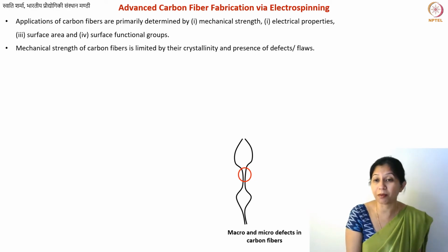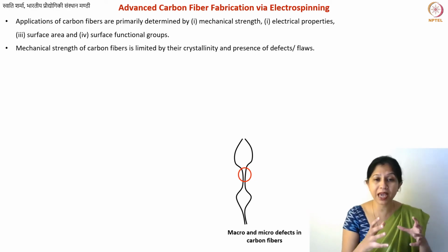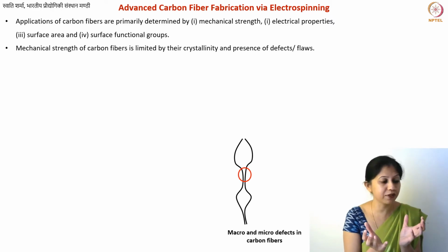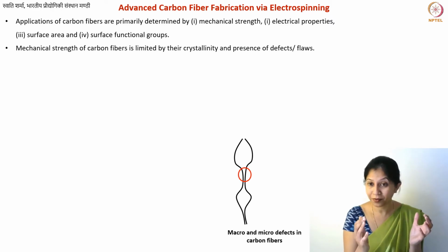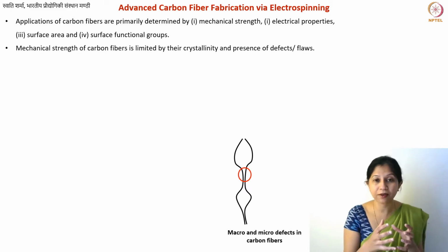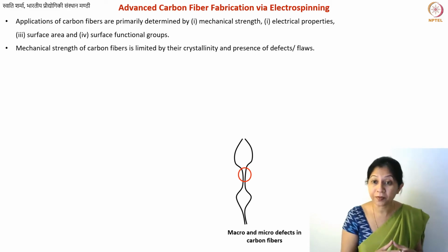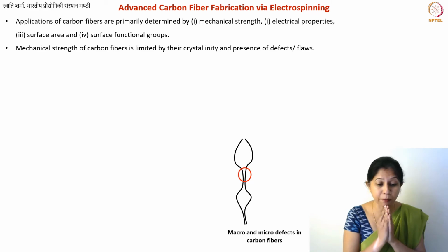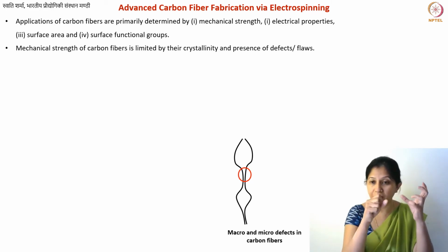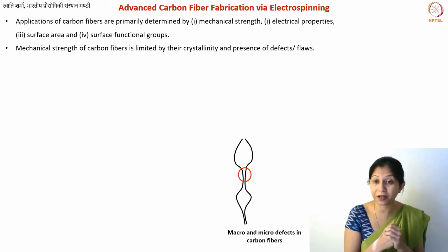Also, these bulges may contain large scale flaws or defects, because they do not have the same surface area as the rest of your fiber, and that is why the defect annealing pattern, the byproduct annealing pattern, everything is different in that bulge. You may even have different purity compared with the thinner region of the same fiber.